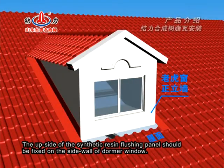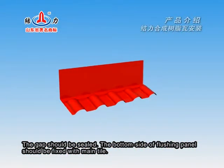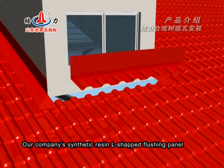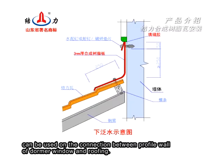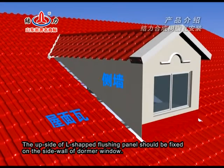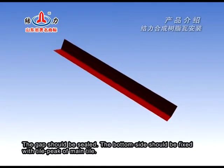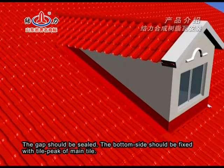The upside of the synthetic resin flushing panel should be fixed on the side wall of the dormer window. The gap should be sealed. The bottom side of the flushing panel should be fixed with main tile. Our company's synthetic resin L-shape flushing panel can be used on the connection between the profile wall of the dormer window and roofing. The upside of the L-shape flushing panel should be fixed on the side wall of the dormer window. The gap should be sealed. The bottom side should be fixed with the tile peak of main tile.